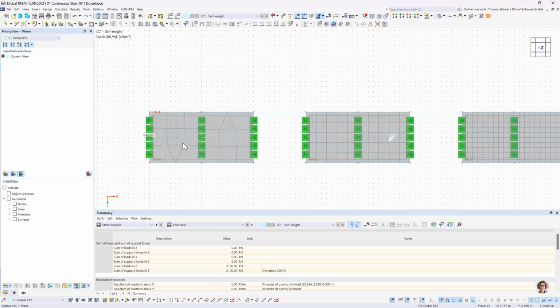But with this element in the middle, we wouldn't have any result in the middle. That means we wouldn't even have the possibility to show us the maximum here, because the next value which would be shown would be this here at the edge of this element. So that's just not good. And that's the point here in the next figure. We can see 5 elements here.